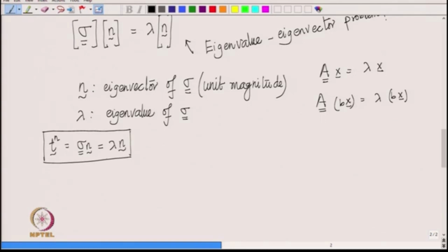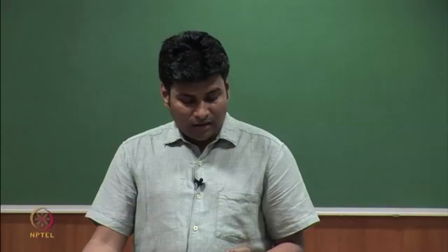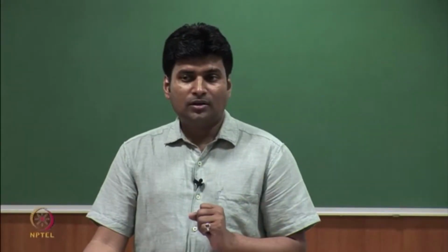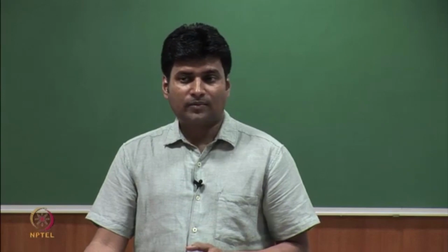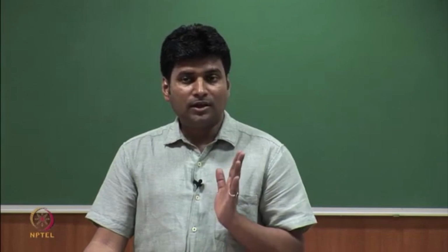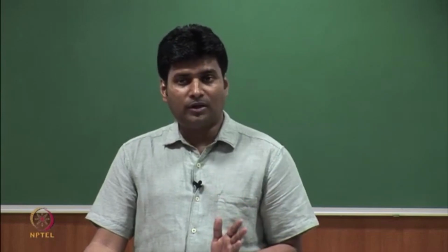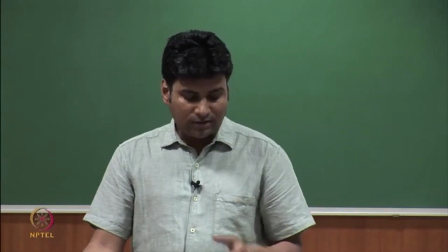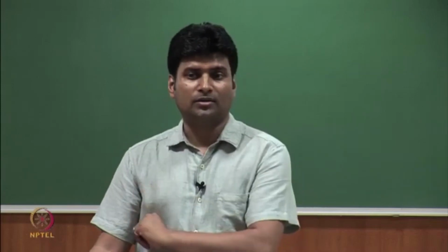So, what we infer is n is the eigenvector of this equation, but now from this box the traction is along the eigenvector, isn't it? So, remember n was the direction of the plane to begin with, which now turns out to be the eigenvector, and now we see that the traction has to be along that direction.